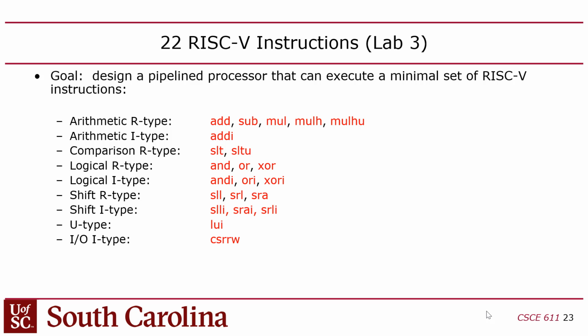Okay, so all these instructions write a register. The only exception is the CSRW if you're setting the hex displays. If you're updating your hex displays, then there's no register being written. Now you might say, wait, what about a no-op? What if you give it a 0 instruction? That shouldn't be writing a register then. Shouldn't be doing anything. Well, it turns out the no-op instruction, which is all 32 zeros,